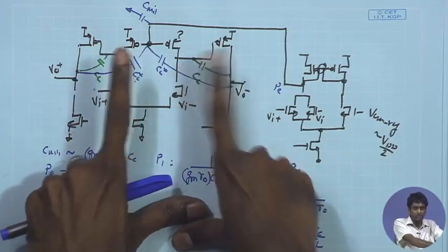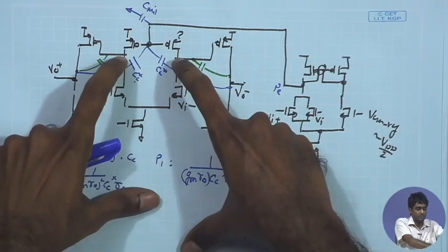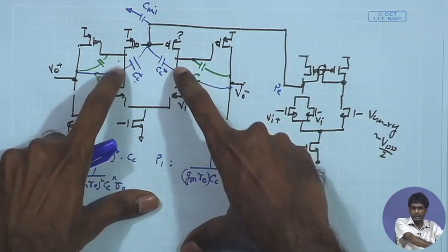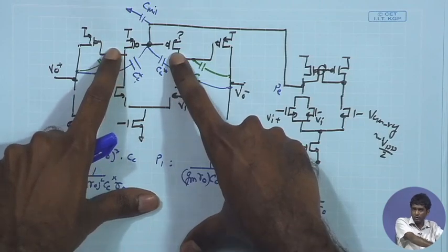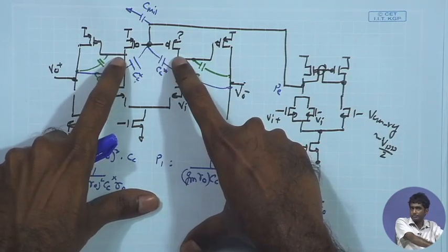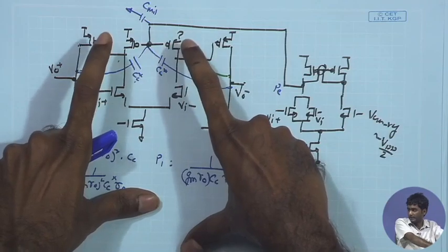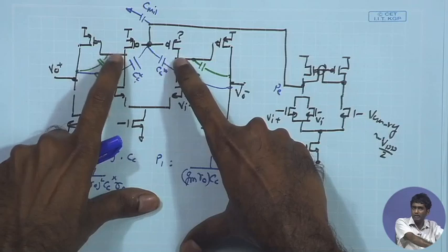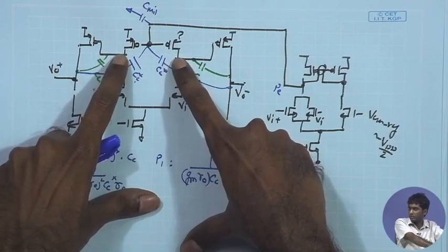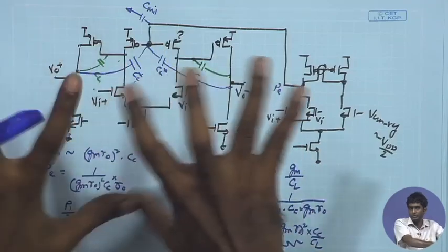So, this is controlled by the common mode feedback, and there one of the other issues is that you do not have a very fine control over this. This can end up being too low or too high, and therefore the transistor over here can end up in triode more easily. Whereas, when you are defining this at a desired point, say equal to VGP, then it is much more ensured, or you are having an appropriate DC point over here. So, that is another advantage of using dual loops.